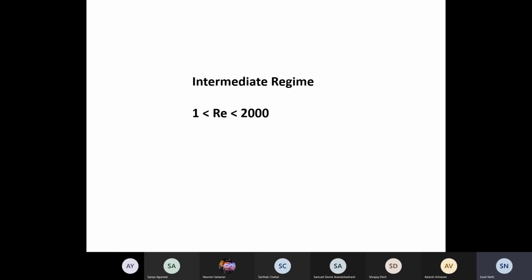So as I said, you can neither model drag force, drag coefficient, etc. in the intermediate Reynolds number region. You can't treat it as Stokes flow. I already told you that at Re equal to 1, we are making 5% error. If you go beyond, the error will start accumulating and increasing. Okay, so I won't advocate using the Stokesian.